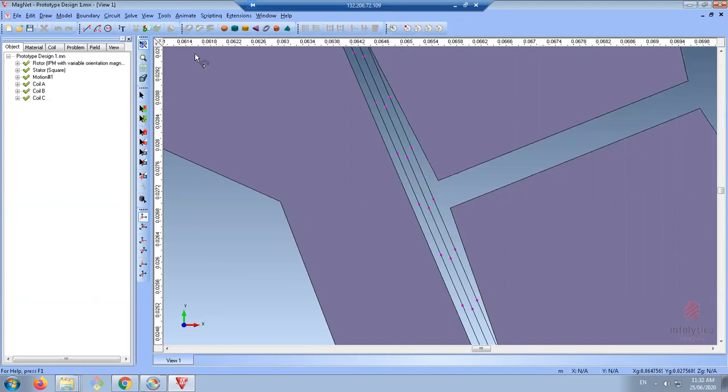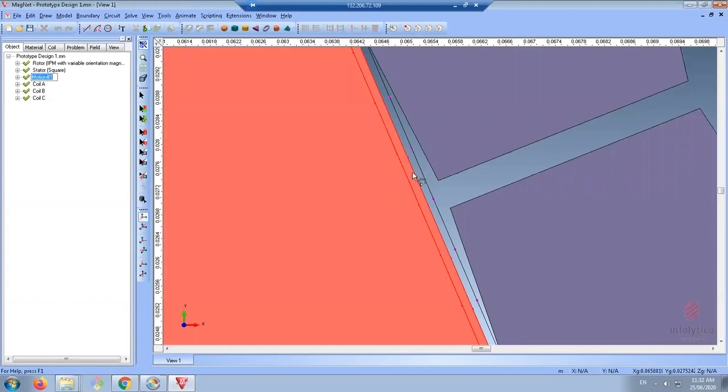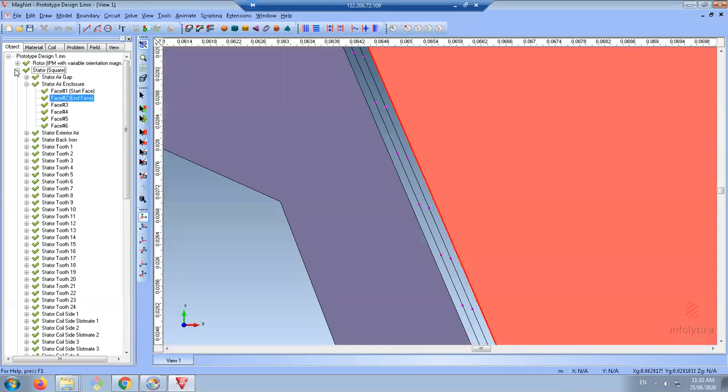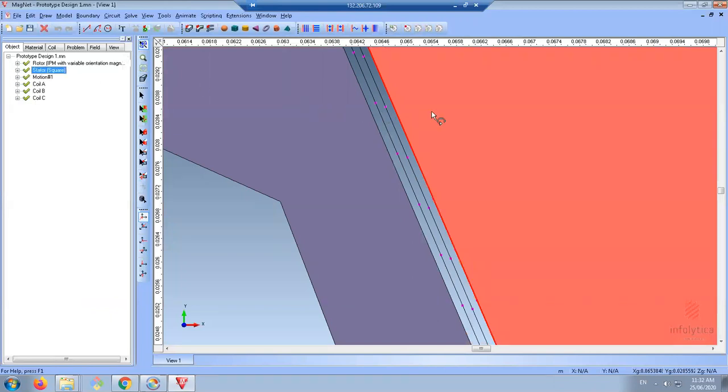the parts. And if we select the motion analysis, as you can see, two inner components of the air gap are assigned to the rotor and the other two are assigned to the stator. The inner parts will rotate with the rotor as we increase the mechanical position, and the other two will be fixed at their place. We do this in the finite element environment to make sure that we have a good torque computation.